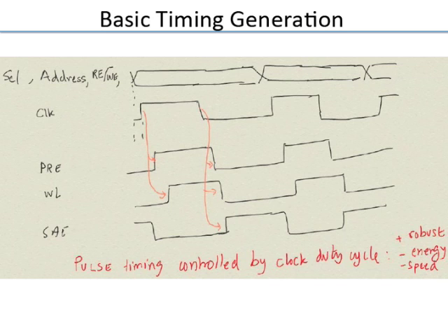So there is a certain relationship which you have to maintain between the signals. That you can do by your circuit implementation. The pull down happens after sense amp goes high, and that signal is used to gate and turn on the pre-charge. That way it will ensure that pre-charge doesn't turn on before sense amp enable goes high. That is basically called interlocking.